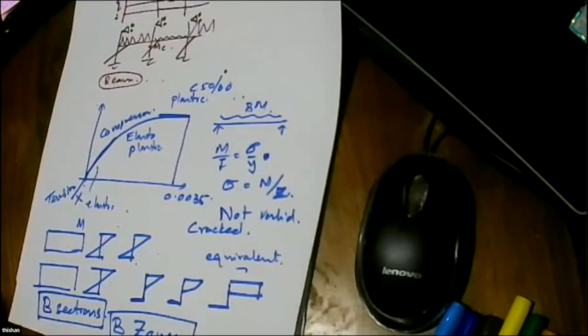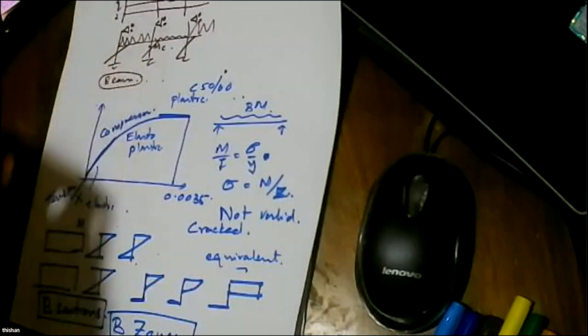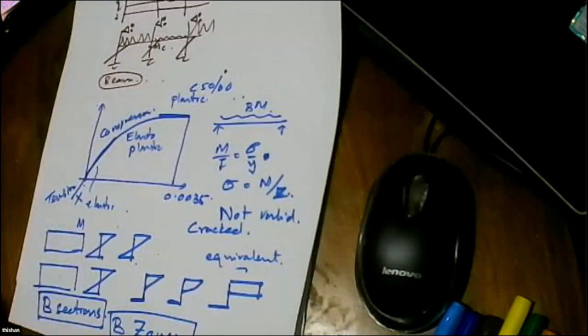So the project was becoming not feasible. Why? The allocated amount is 1, the cost is much higher, and if you spend too much money on the foundation, then the project will not have enough money to do the remaining part of the structure. So there's a big problem. Then I got involved, and we looked at our experience with Altea, where again the rock is fractured, and we went up to 10 meters of rock socketing. We thought, okay, let's look at it differently.